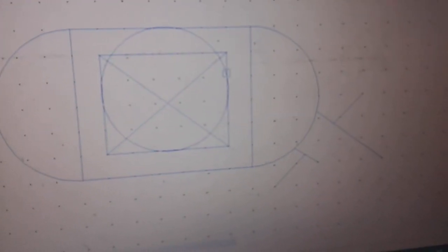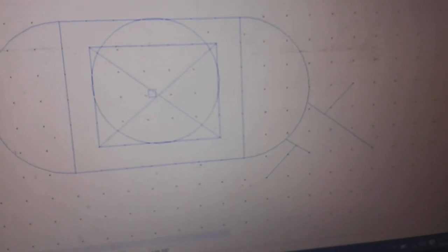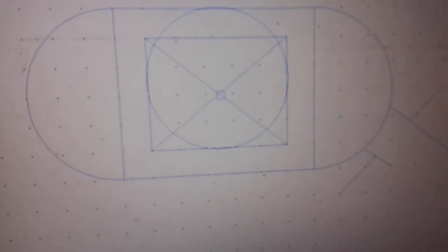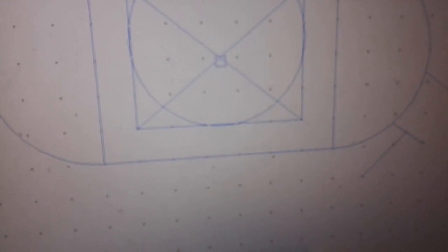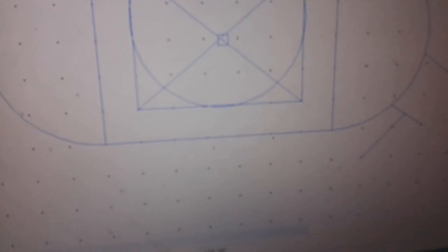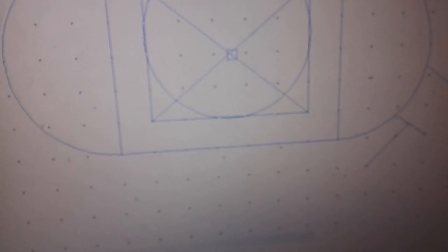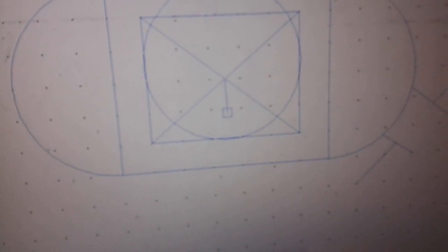So I go over to here and click the grid once, and it turns a light color, and then my cursor will move around wherever I want it to. I can then highlight that box right over the center crossing like that. I don't have to be that accurate. I just have to make sure that my square box covers that center crossing. And then I click a left-hand mouse, and the line will snap directly to that point.